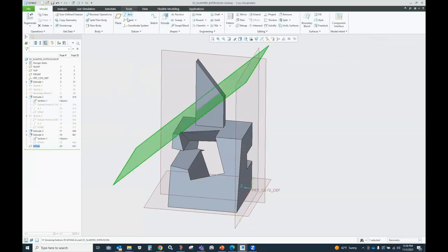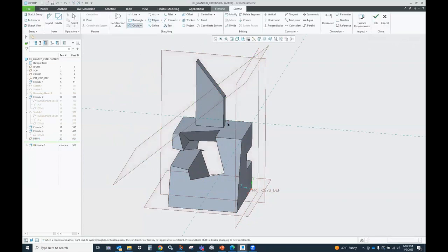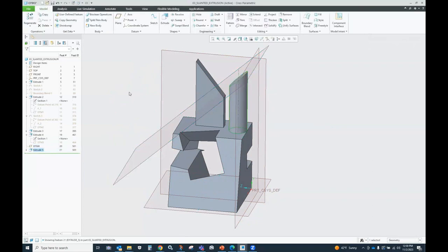And then I say extrude from that surface, and we'll do a circle. And I'm going to say 2. I'm dragging and holding my shift key. Boom, there it is. As long as there's nothing else using that datum plane, I can drag it inside. Okay, good, perfect. So you can go back and clean up all your models if you want.